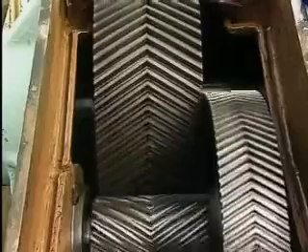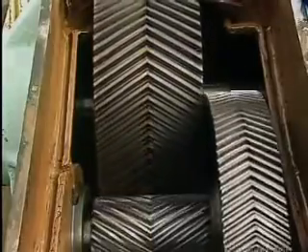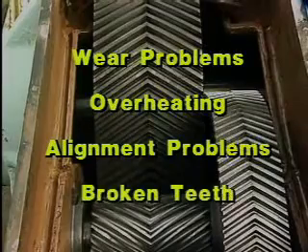Just about all gears will experience some amount of end play during operation. In fact, some amount of end play is desirable. For example, a small amount of end play will allow the parts to expand when they heat up during operation. However, too much end play could prevent proper meshing of a gear and pinion and could cause uneven wear problems, overheating, and alignment problems. Severe cases of axial movement can even cause the gear teeth to break.